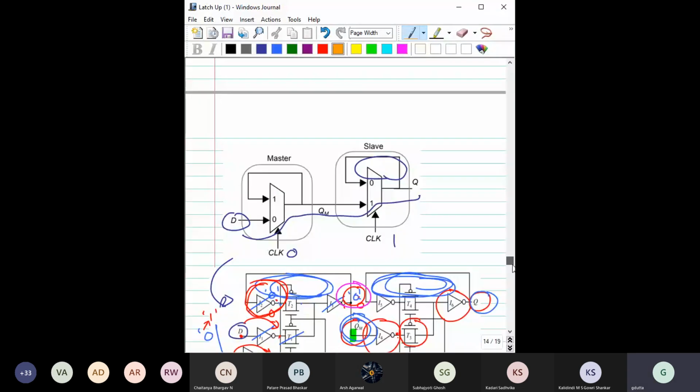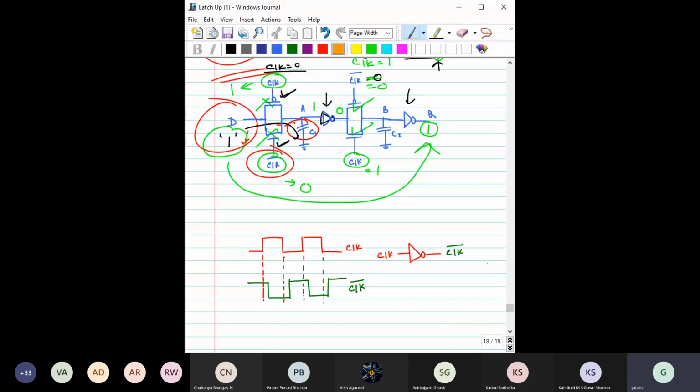Okay. That is for the static case, master slave, right? Here, how many transistors? 1, 2, 3, 4, 5, 6, 7, 8. Right? So the total number of transistors required is significantly lower for the dynamic register compared to that of the static CMOS register, right? So that is obviously an advantage. More transistors mean more area, right? More delay, more power dissipation.